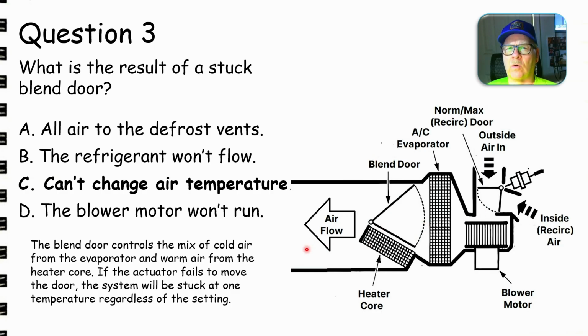If you've ever had an old car or one the AC doesn't work on, when you turn that thing on defrost, the compressor is supposed to kick on if you got AC anytime it's on defrost, even if you hadn't turned on the AC. When you turn on defrost, the compressor kicks on, it dehumidifies the air, and the air that hits the glass is real dry, and that really helps out.